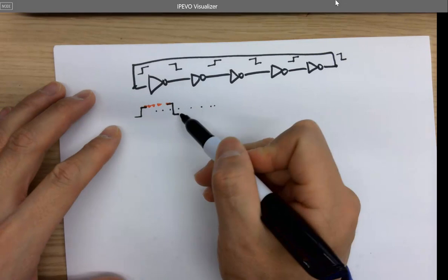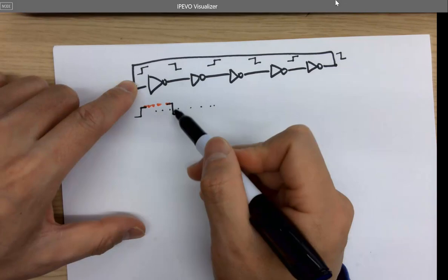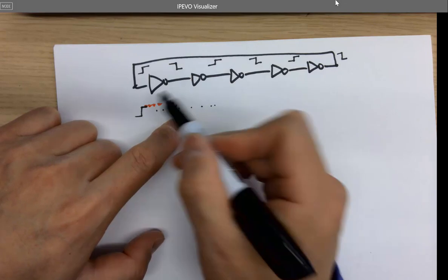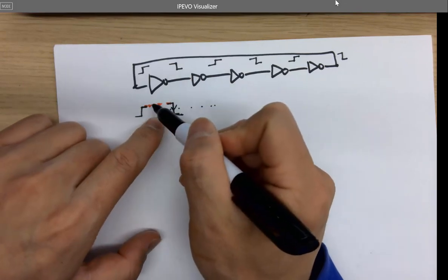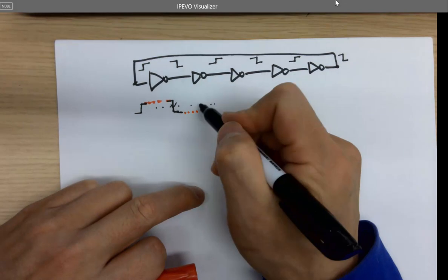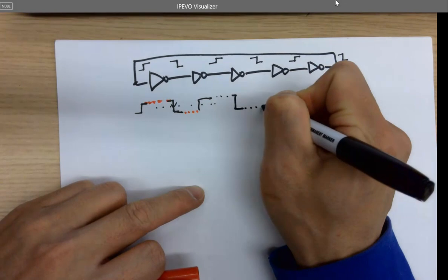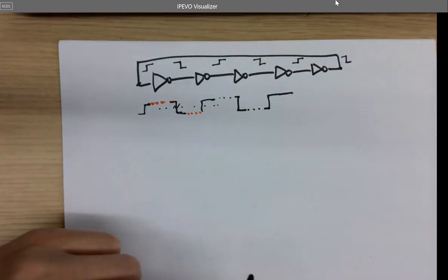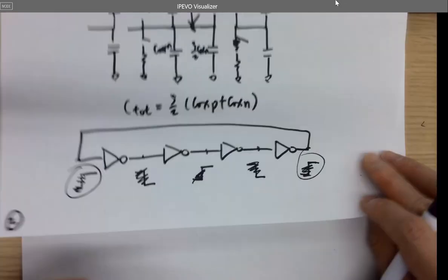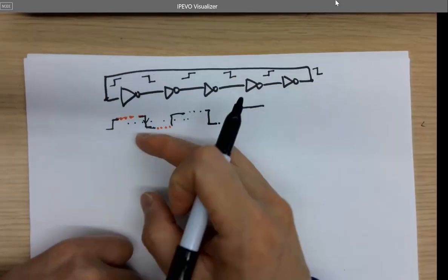So this is from low to high, right? But after a while, it goes back to 0, okay? And then this one will be delayed in the same way as whatever the 5 volts is getting delayed. So it's being delayed through all the inverters, and eventually it will go up, and then it will be delayed and will go down, and delayed, go up. So what's happening? It's oscillating, right? It's not stable. It doesn't like the even number of inverters in the ring. That one is very stable. It's a latch. But this one is not. It's oscillating. It's not stable.